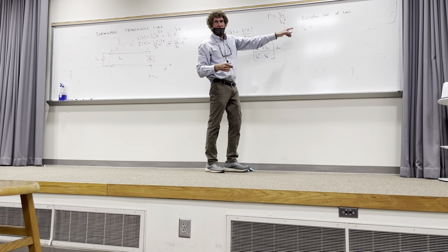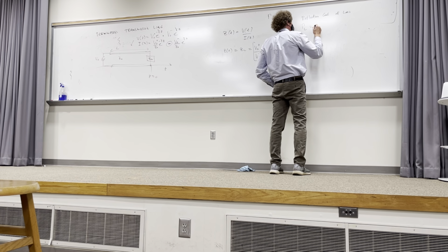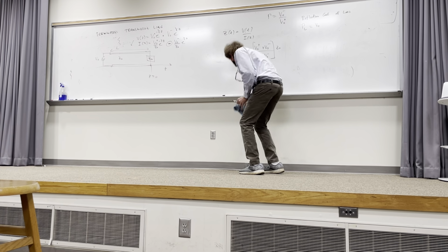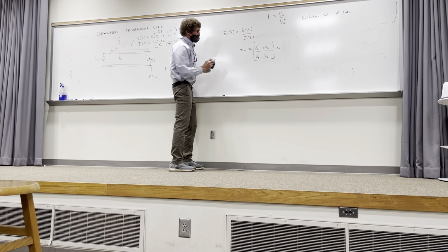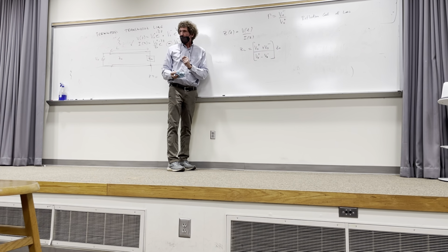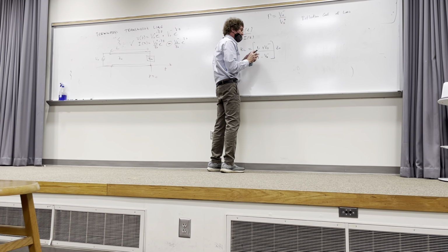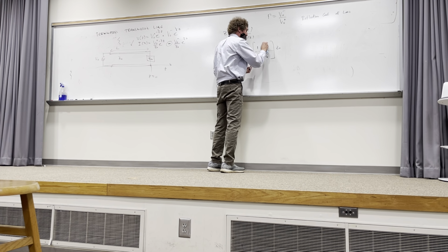So when I talk about gamma L at the load, it's really the ratio of V, and let me do it this way so you can see it better. Y'all agree that this is true right there, right? All right, now, don't write this down yet, just listen. I'm going to divide everything on top and bottom by V0 plus. So I get a 1 here, and then I get V0 minus over V0 plus. Y'all follow me on that? That's going to be gamma.